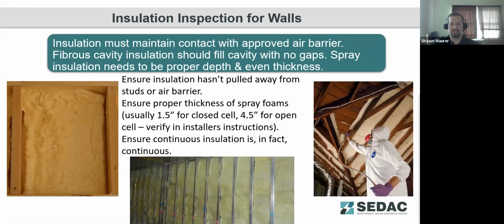For spray foam insulation, they're going to be checking for proper depth, that the insulation hasn't pulled away from any surfaces. As you can see on the left side here, as the foam is cured, it's pulled away from the studs and left air gaps. And so you don't have a continuous thermal layer there.